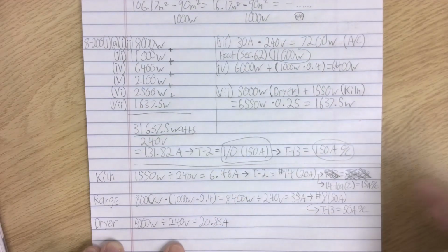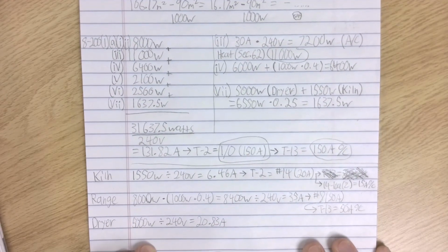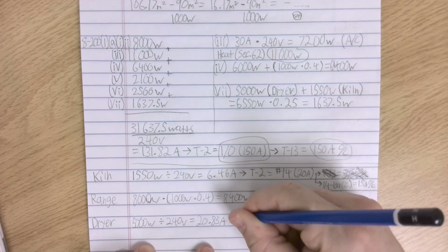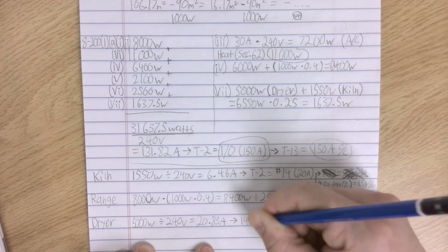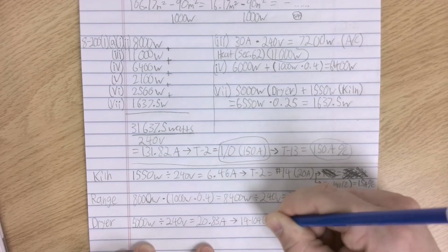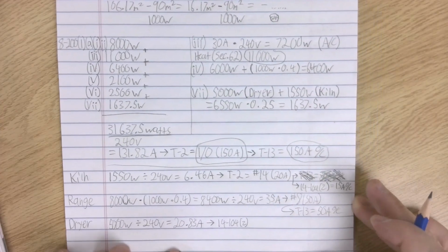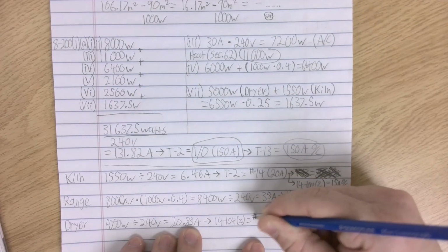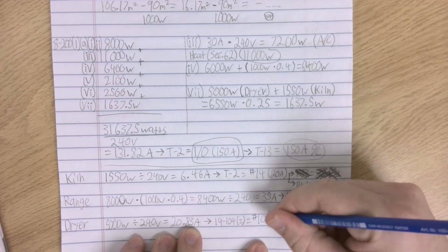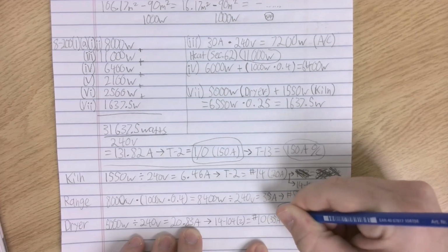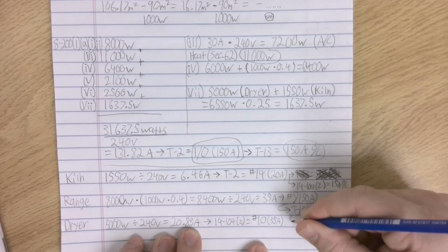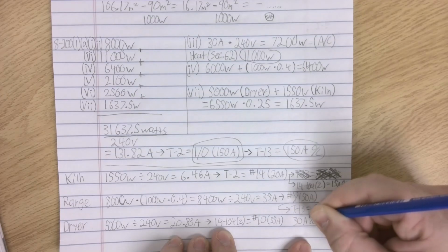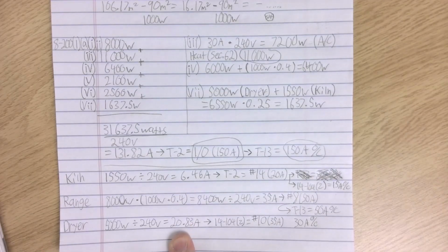I'm not even going to look at Table 2 or Table 13. I'm just going to remember 14-104, subrule 2. And you don't have to memorize that, I just have from use. So that's going to give me a number 10, which I still know is good for 35 amps. I'm still going to put that there. But I also know that it's going to be a 30 amp overcurrent because that's above 20. So number 12 isn't going to cut it.